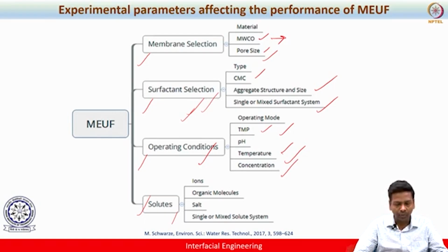One should also be wary of using too much concentration, because the solution becomes more viscous, and there will be more pumping cost, which becomes a costlier affair. That's why one has to choose the right operating conditions for the process.